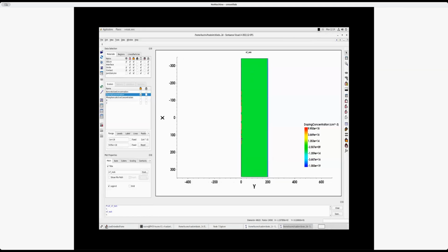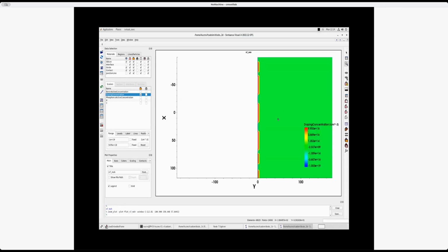So now I get the rendering of the colors, and I can look at my device, so we can interact with the device that we just generated. Can zoom on the pixels here, for example. So in that case, what we have is 3 pixels and kind of a guard ring, which looks like a pixel but has a different metallic structure, with an N-type doping under each of the electrodes and a P substrate.